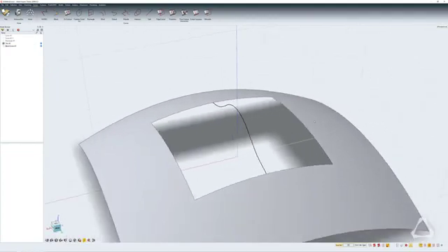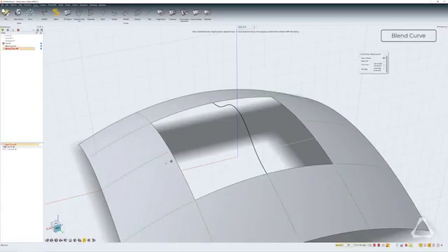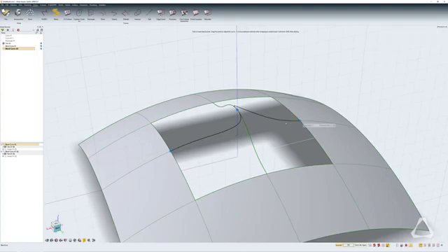and we're going to repeat the same process on the other side. If we want to add another rail curve, go to the blend curve tool. Now I'll disable the grid snap again, just move to the midpoint, snap, and here I can snap the second point directly to the midpoint of the old blend curve, and then finally here onto the other midpoint. Right click, swipe.